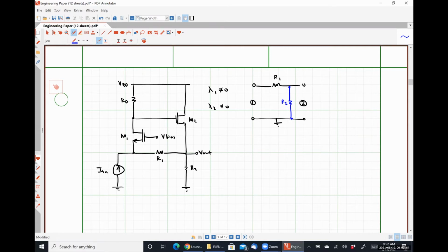So I will give us both. So R11, when we look at it with just resistor 1 as our feedback network, remember we're looking in through port 1 with port 2 shorted. So what should we see? R1.